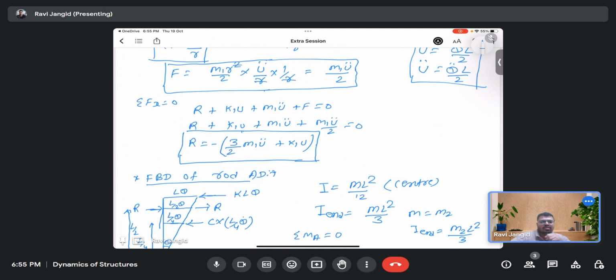Okay. So you are asking for the time history. Time history analysis is a very good estimation for finding out the response, but it is time consuming, it will take longer time. The response spectrum analysis is not as good as the time history analysis, but in that you do not need much, it is not time consuming. In the response spectrum analysis, from all the time histories, you can make your response spectra corresponding to your target spectra.